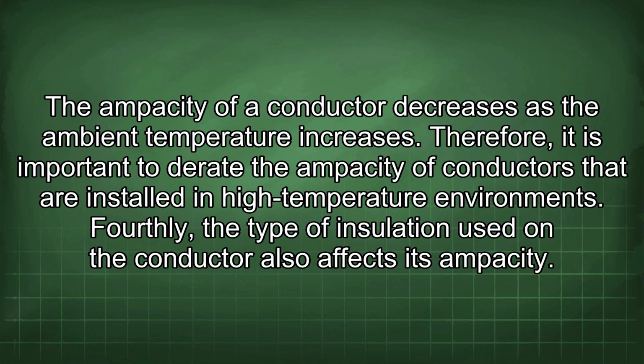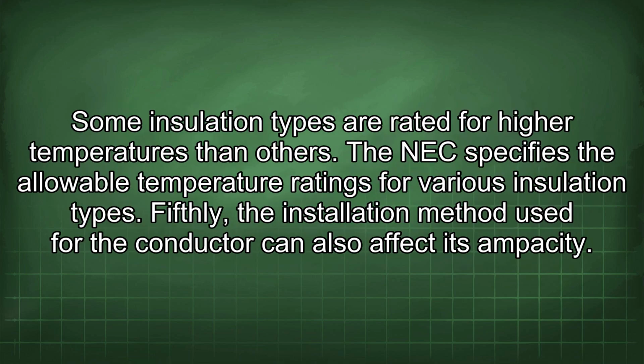Fourthly, the type of insulation used in the conductor also affects its ampacity. Some insulation types are rated for higher temperatures than others. The NEC specifies the allowable temperature ratings for various insulation types.